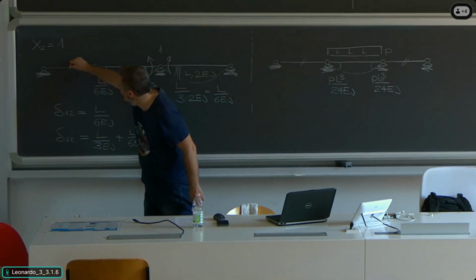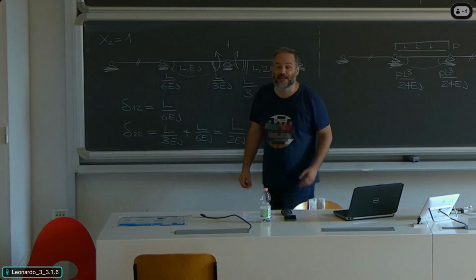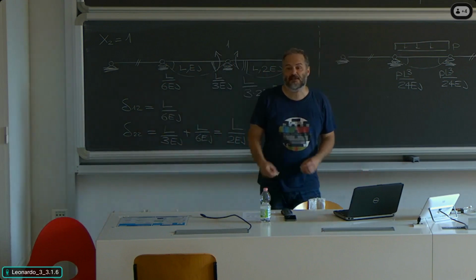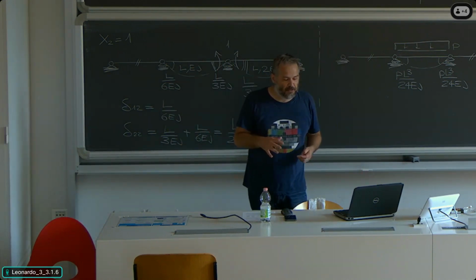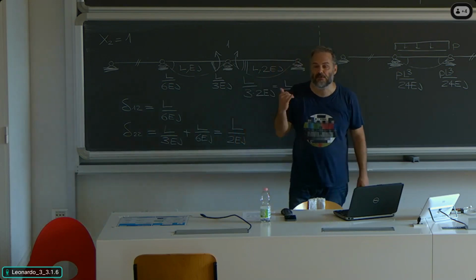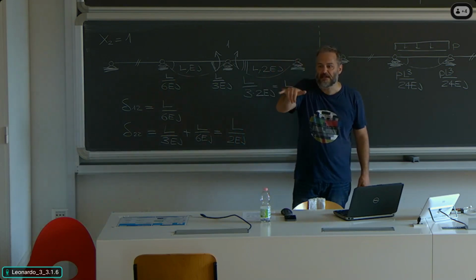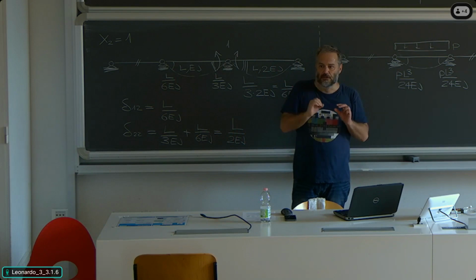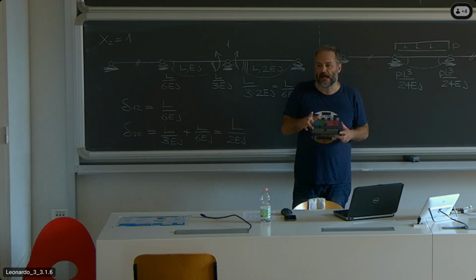Same takes place here. As a matter of fact, this way of solving continuous beams is exactly meant to make things simpler. In this way, everything is limited to the portion of the structure where the load is applied, be it an unknown or an external load.